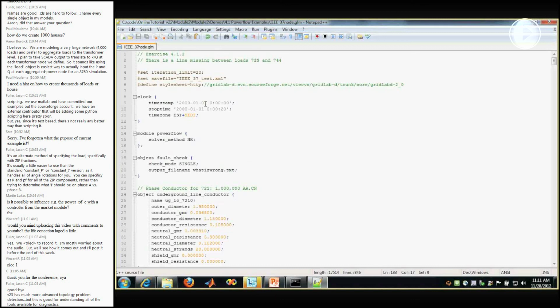And that's a little more difficult to track down. The best way we usually do to figure that out is exactly what I showed you, where you put it in forward back sweep, and then you go look for something that has a nominal voltage where it shouldn't. And that's a good indication that it has made that a secondary swing node, and something's missing connection-wise, or you actually have two systems in your file instead of one.